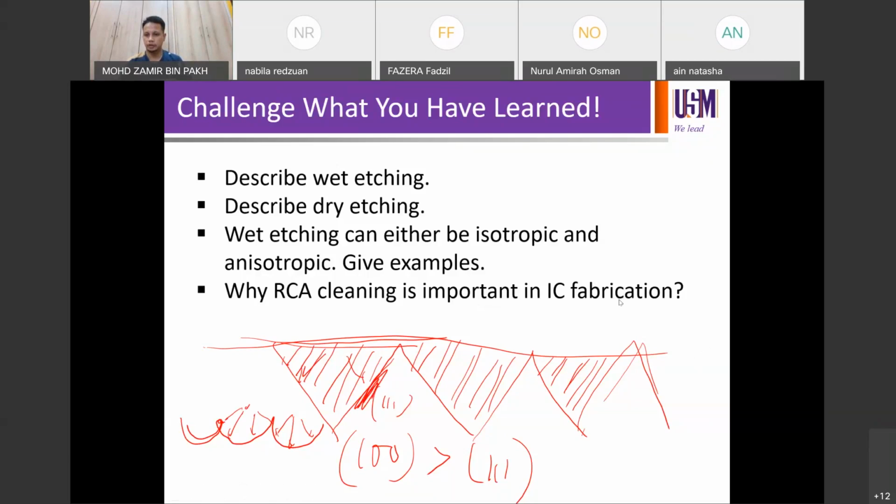Hazika, can we do a conclusion? The anisotropic, we use alkali solution, isotropic. Yes, exactly. Right, you picked that up. Usually for isotropic etching, we use acidic etch. For anisotropic, we use alkaline etch. Exactly, good. Right? So that's how it goes.